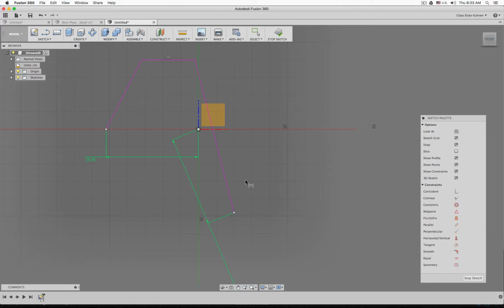Not a big deal. So what's happening is the sketch solver tries to figure out how I want the sketch to be manipulated, and I do not want this point to be going down, I want this one to be horizontal. But with the sketch solvers, we need to restrict movements as much as possible. So this point and this point, they should always be horizontal.